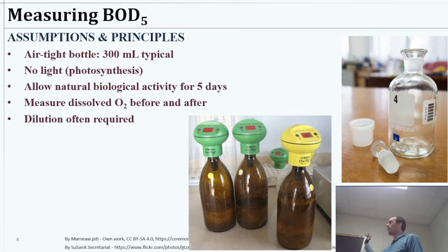And so then what will happen is as you're measuring the oxygen over time, you started at 8 to 10 milligrams per liter, you dropped all the way down to approximately 0. Really, your reading will probably say, oh, it's like 0.5, but the measurement just can't detect lower than that. So that's just what it's giving you. And so at some point, you have to have a hard limit to say, okay, well, we can't go below that. So we have to then dilute.